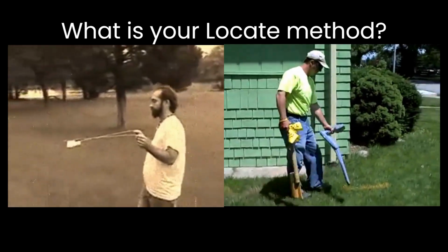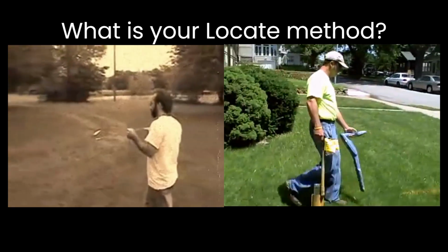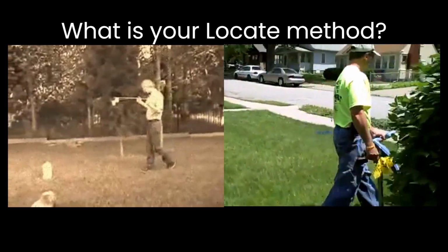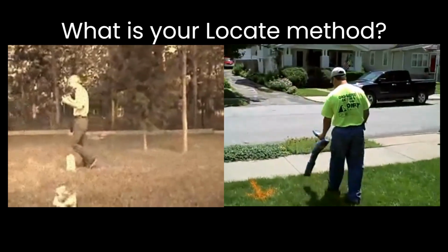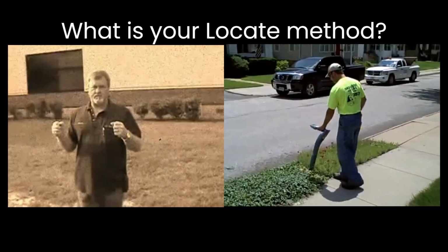And so we're advancing that primitive technology into a cable and pipe locator, and we're able to use an identifying frequency with multiple antennas in the receiver that will receive that signal, that magnetic field, and be able to measure it, giving us a depth, a current measurement, and other checks and balances.